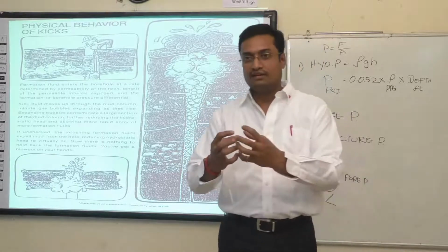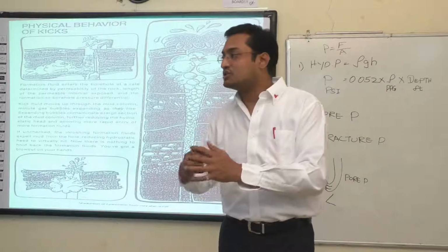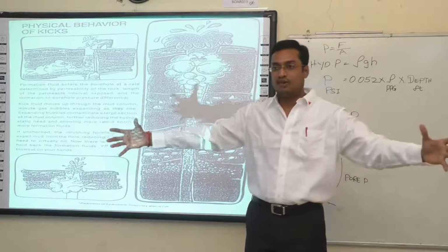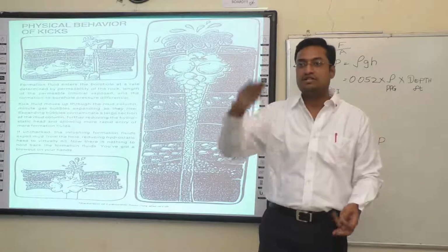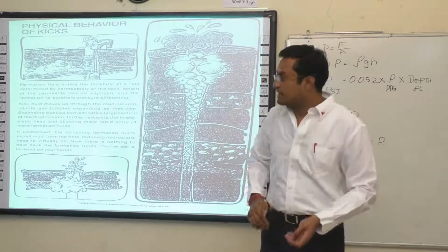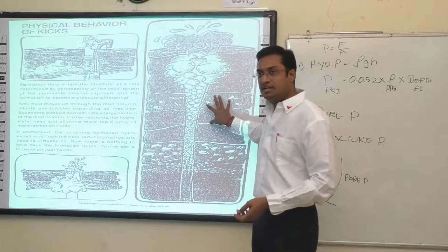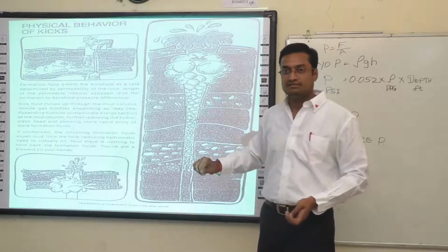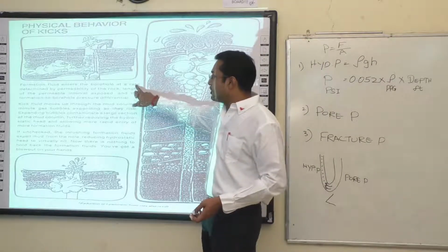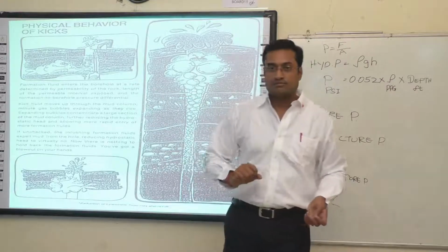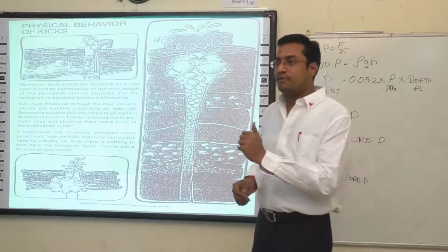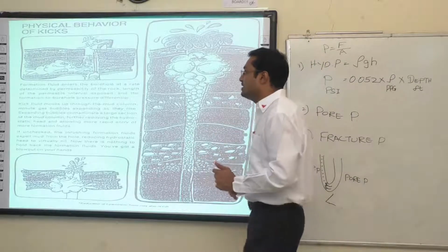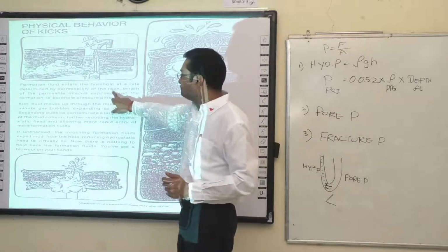You get a kick, but it is not well supported by the formation, so it will subside. The intensity will reduce. But if it is highly permeable, the intensity will be very high. So the formation fluid entering the wellbore, along with the permeability of the formation, decides the intensity of the kick.